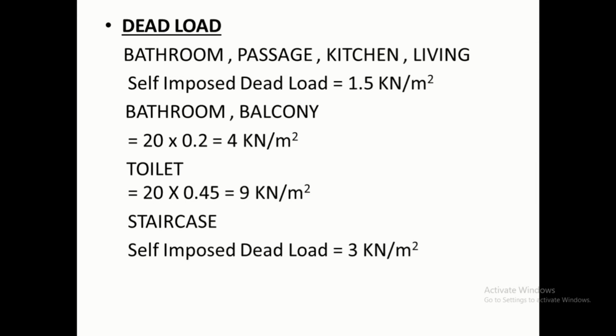All these values whichever I am going to say are completely according to the Indian Standards, that is, according to the IS codes. For dead load, for passage, kitchen and living, the self-imposed dead load is equal to 1.5 kilonewton per meter square. Actually it's not bathroom, it is for passage, kitchen and living.